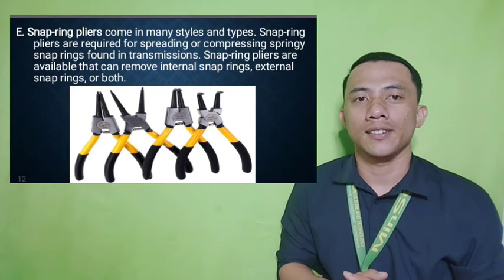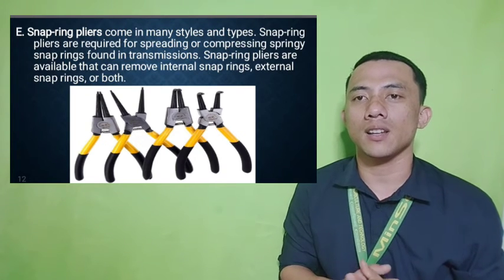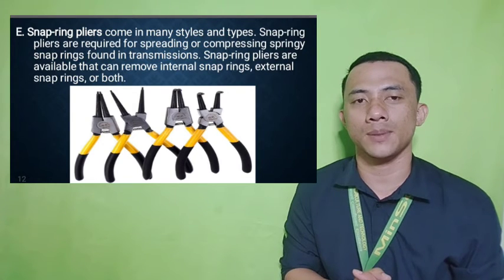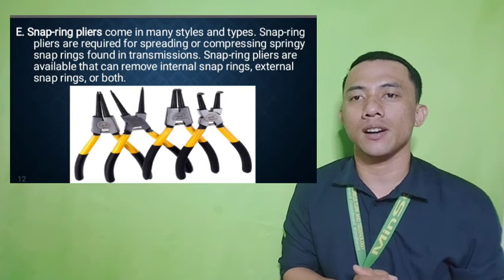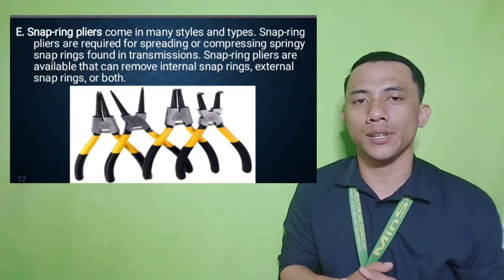The last one, we have the snap ring pliers. The snap ring pliers come in many styles and types. Snap ring pliers are required for spreading or compressing springy snap rings found in the transmission. Snap ring pliers are available that can remove internal snap rings, external snap rings, or both.